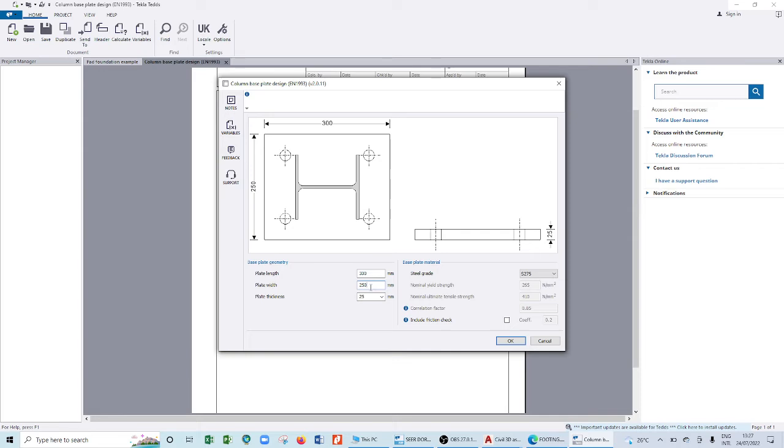These are edge distances. The center of the hole from the end. If the center of the hole from the end is small, it's dangerous, because it can tear off. So you are pointing to the minimum edge distances. You have to be conscious of it.